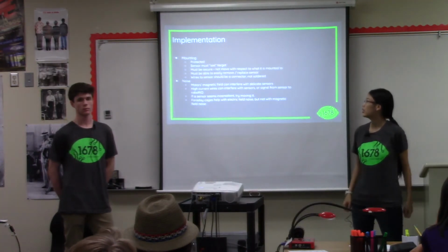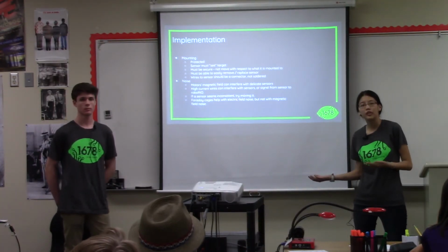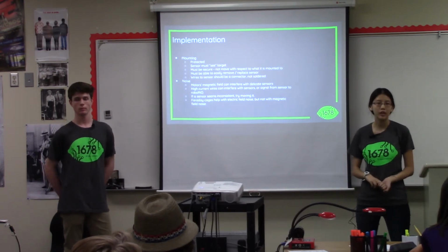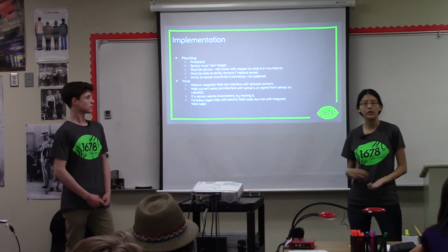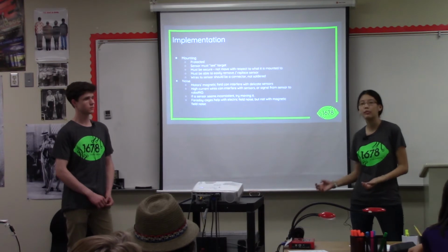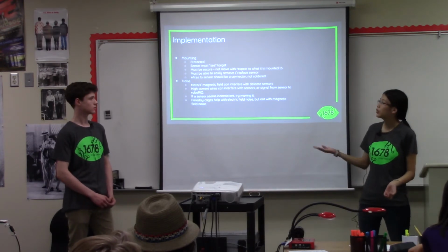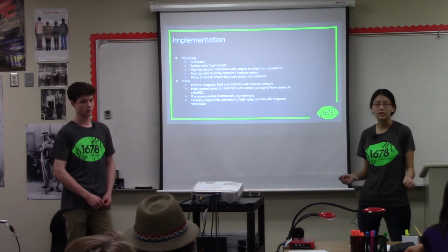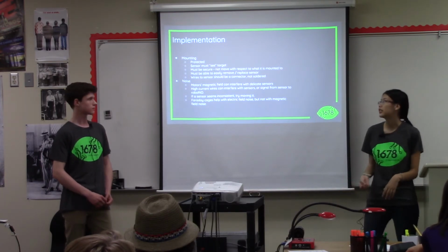And the sensor must be able to be easily removed. For example, we've had sensors such as proximity sensors and encoders break. If you need to replace them, you need to be able to replace them easily without taking apart the entire robot. That's why we also use connectors for sensors instead of soldering, because that way we can disconnect the sensor easily and replace it just as easily.